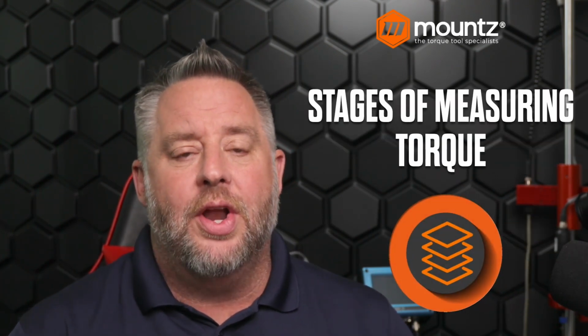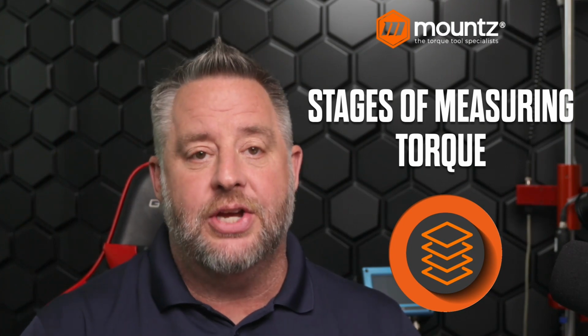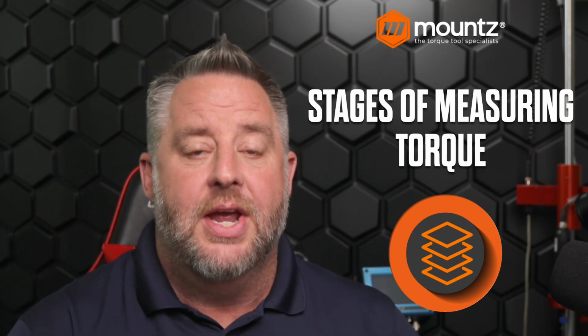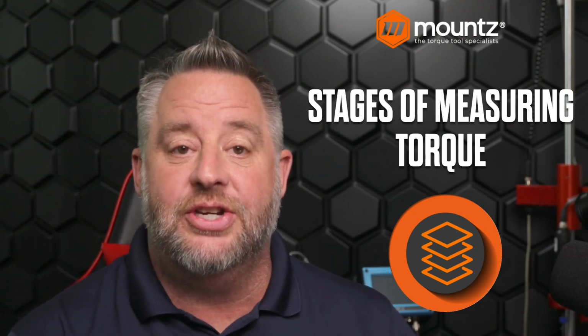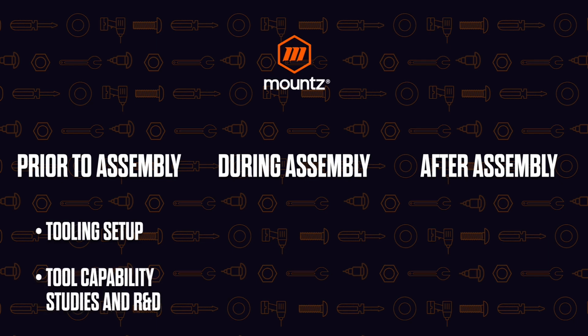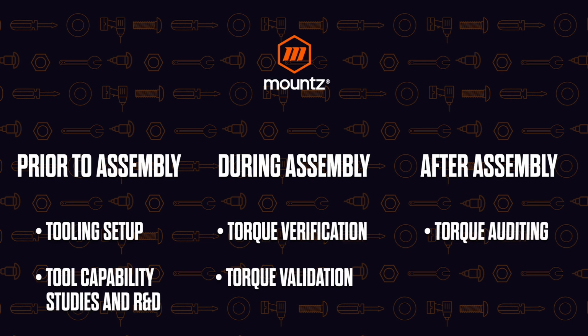And so what are the different stages throughout the application process that we can use our torque analyzer to measure and gather torque data from? There are three basic stages for that. First is going to be prior to the assembly, next during the assembly, and then you guessed it, after the assembly. Prior to the assembly, we're looking at the way we set up a particular tool for an application. It can also be used for tool capability studies and R&D. And then during the assembly process, we're looking at the torque verification and torque validation process. And then after the assembly, we can do some torque auditing and then torque recalibration for a specific tool.